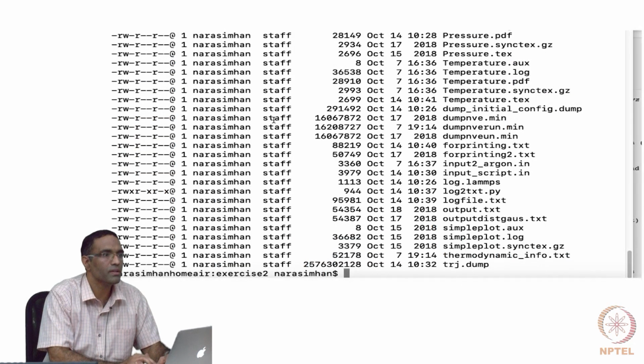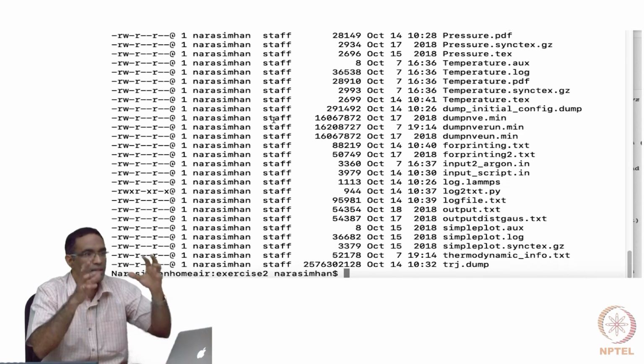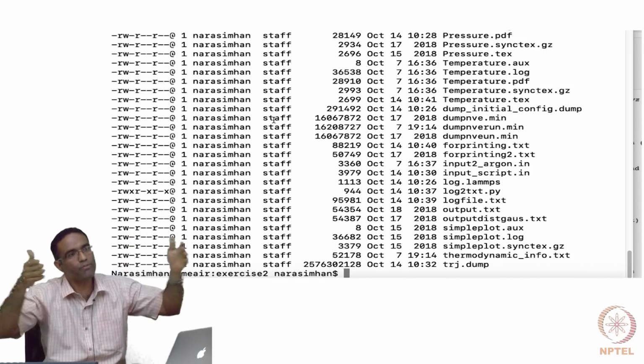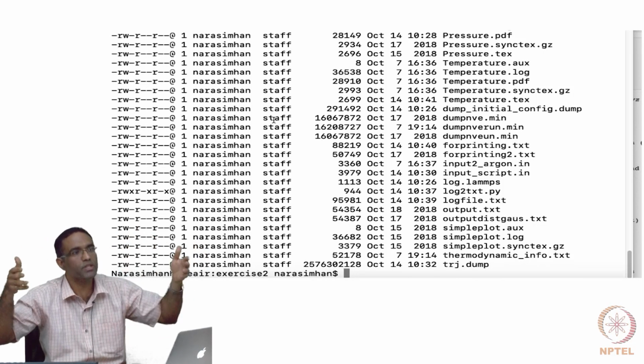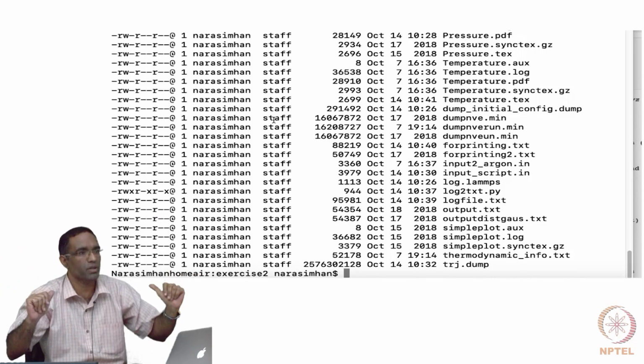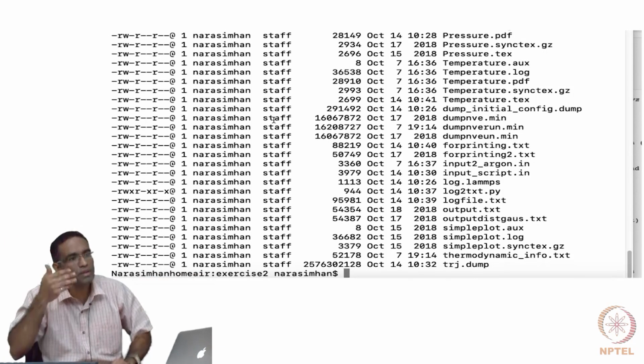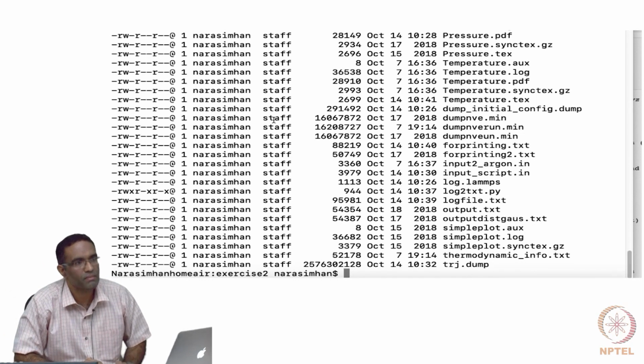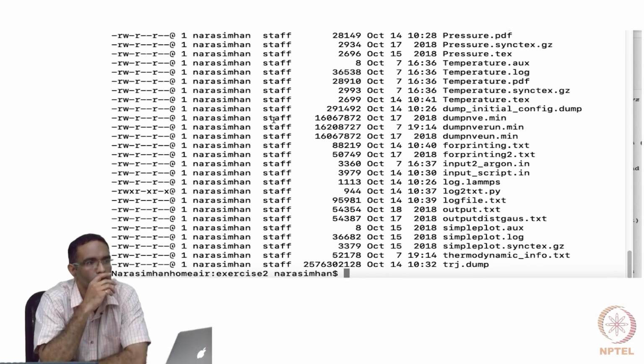Why is that? Because you program it to run till 300. Yeah, but what is happening is it is constantly pumping in some energy, but the time for which I have done it is not sufficient for it to actually reach that temperature. So if you increase the number of iterations with the same command, it will. Like, this is the command: say the pressure is 1 bar and the temperature is more than 300, break the iterations even if you give more iterations.